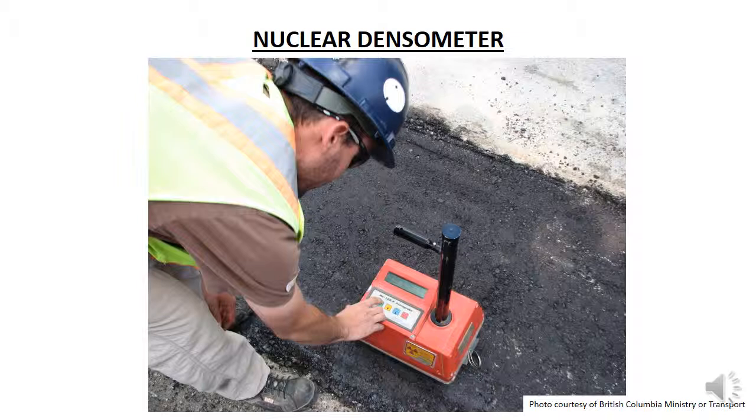So we can measure the strength of the aggregate layer by measuring its density. Measuring density is easier than measuring the strength directly, so we measure density when compacting to give us an idea of how close we are to the required strength. We usually test the strength of the layer directly using CBR or other strength methods when we consider we have reached the required strength. The measurement of dry density in the field is undertaken with a nuclear densometer.